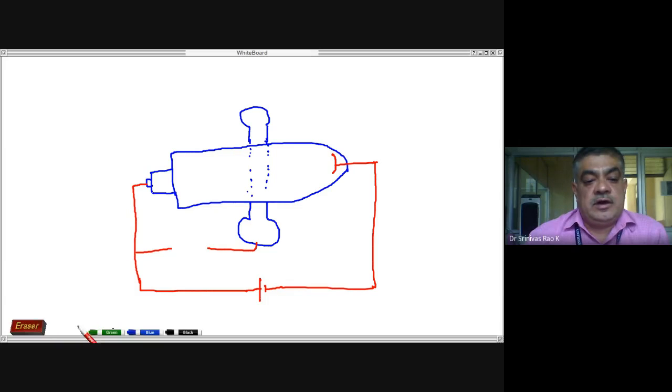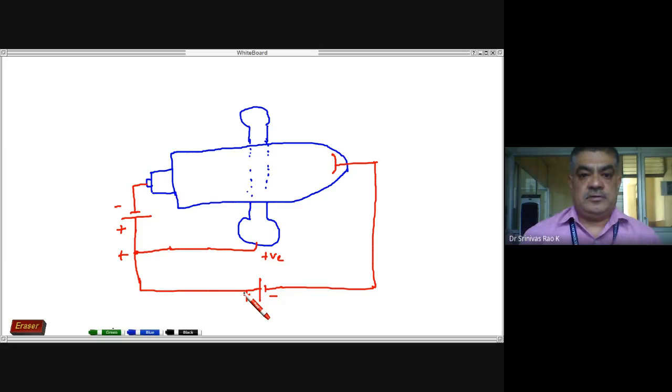I told you in the other circuit, somewhere the mistake has been done. They have repeated all the mistakes. One college has made the mistake in the notes, every mistake. See, this is the negative and positive here. Here positive, negative. Here also positive, negative. So now you can see the same terminal here also has positive voltage. Everywhere positive is there. So here also positive. Now we cannot have negative here. If I have negative, then I cannot have negative and positive terminals joined together. It will be a short circuit. So this is an absolutely wrong concept.